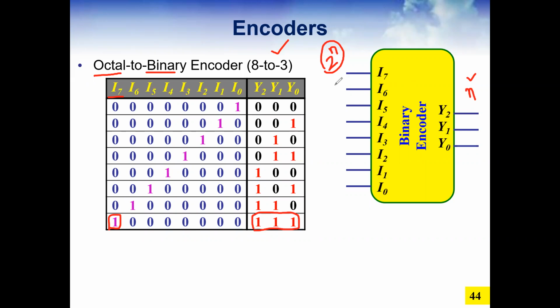So this encoder is converting an octal number into binary. Let's check what 6 in octal is in binary. We press 6 at a time, put it at 1, and the rest are 0. The output generated is going to be 1 1 0. It means that is the binary value of octal 6. So it is what we call an octal to binary converter, or encoder.